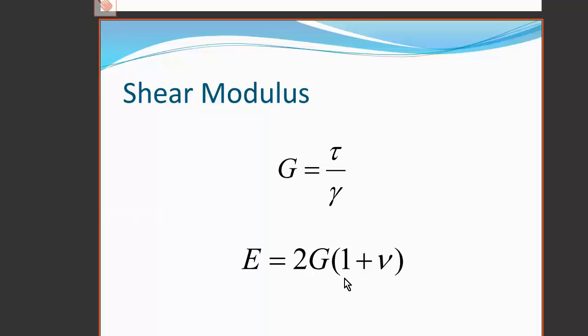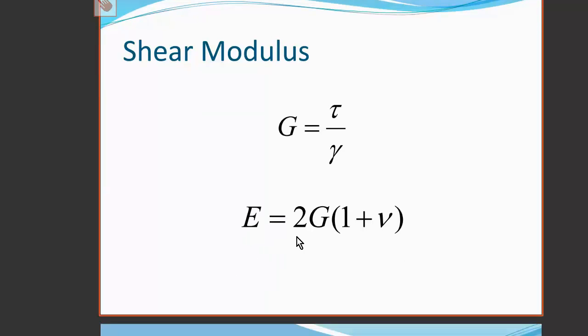We create what is called a state of stress, in which there exist different ranges of shear stress and normal stress in different directions in the material. And this is shown by the fact that the shear modulus and the elastic modulus are related to Poisson's ratio by this equation, showing that shear strain and normal strain are related.